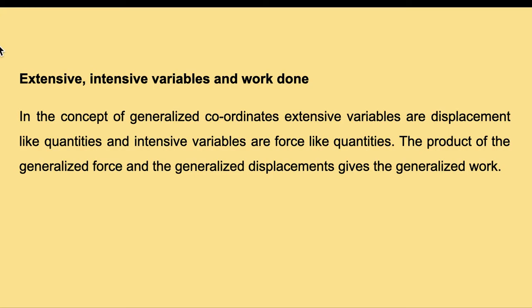In our syllabus, we have to discuss only the hydrostatic system. In thermodynamics, you can also consider an electrochemical cell, surface film, etc. as thermodynamic systems. There also, you will write one intensive quantity in place of force and the change in an extensive quantity, d of that quantity, and that product will give you the expression for work done.